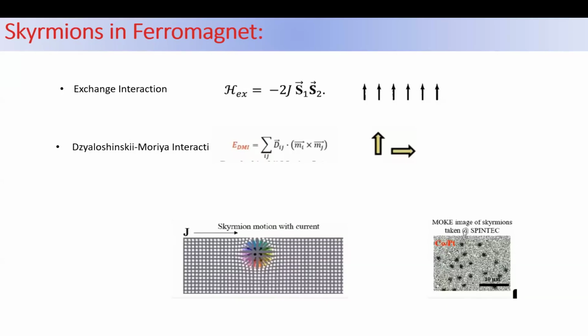So if we try to manipulate it by some external force, like I'm considering the use of current to move the skyrmions. By the application of current, we can move this skyrmion from one end of the device to another end of the device. The skyrmion moves in the direction of current applied itself. And by the movement, it is like the magnetic moments are flipping their directions.